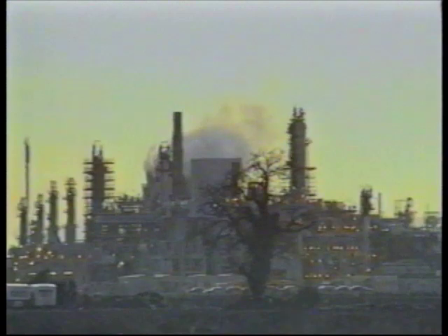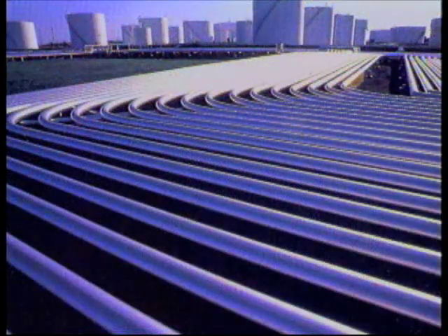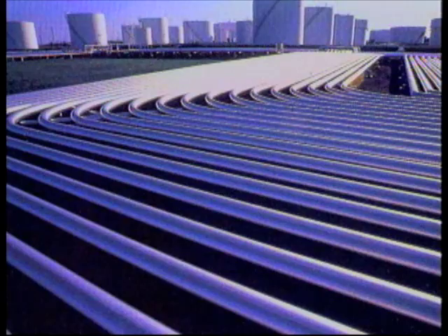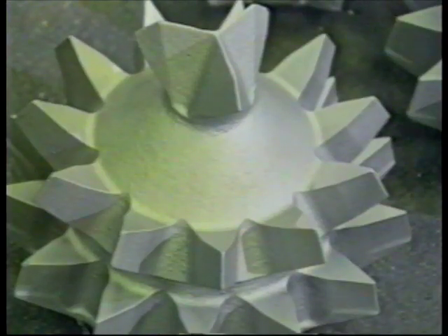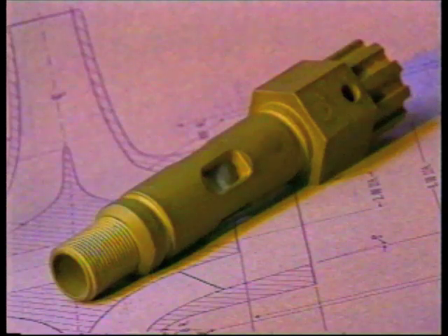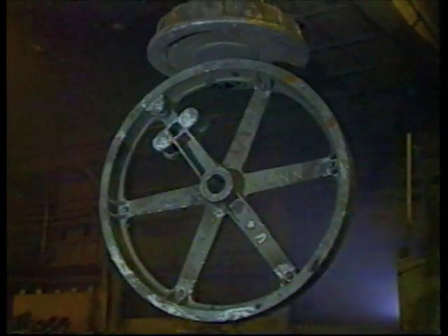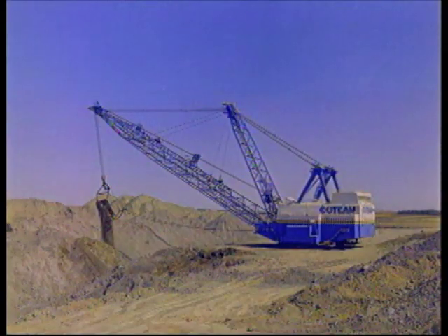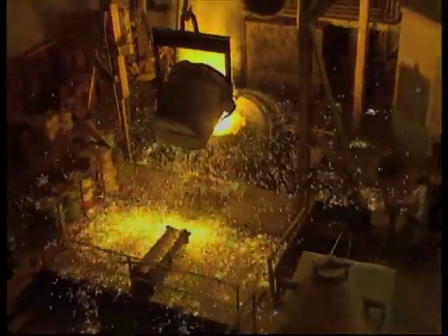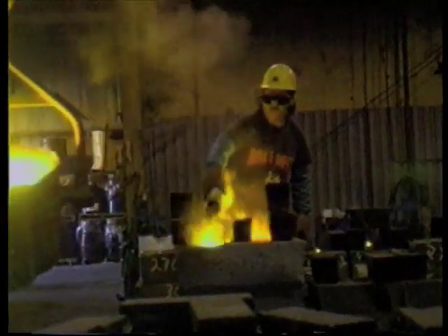Other unique properties obtainable with steel castings are corrosion resistance and the ability to handle high-temperature applications using an ever-growing list of stainless steel alloys. Cast designs can produce parts as small as a heart valve or as large and complex as a turbine casing. Massive components of over 100,000 pounds are used in applications such as the giant dragline. Steel castings offer versatility of design with the strength and service performance of steel. Modern foundries are capable of producing this wide array of steel alloys for the designer's needs because of precise control in melting and heat treating.